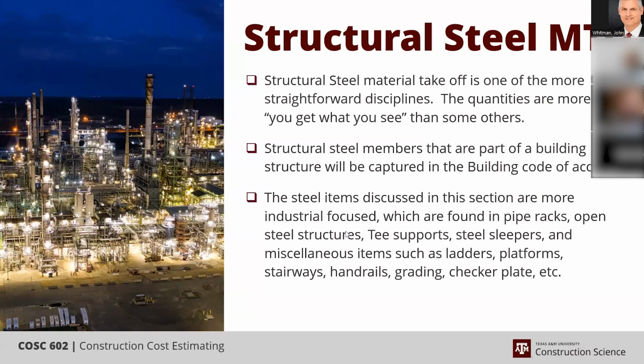We typically put anchor bolts in with the concrete because they're an embed, so they aren't actually concrete themselves. Obviously, they're steel like the rebar, but once the pour is complete, it becomes a monolithic item, which falls under the concrete account.